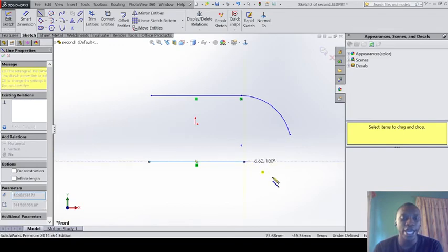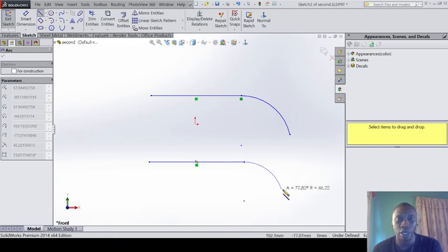So try and draw and stretch a line, but don't left click so that you can create the line. Go back to that point and it will automatically change to an arc. But there is something you should notice. Whenever you want to draw the arc that will be coming out, just slightly move your hand in the direction of the way you want the line to be curved. For example, I can curve it like this. So I'll just move my hand like this. So that's how I go about it.